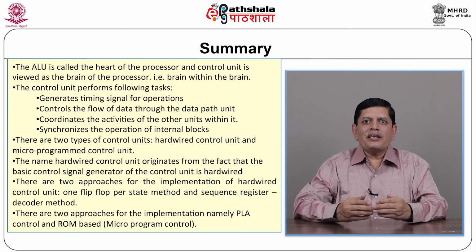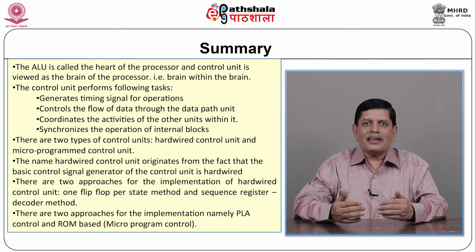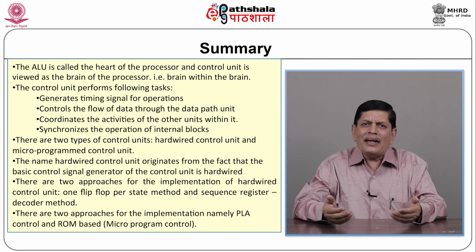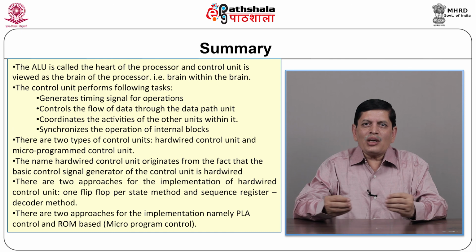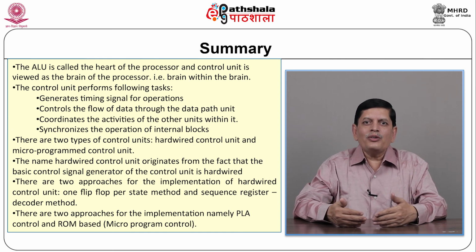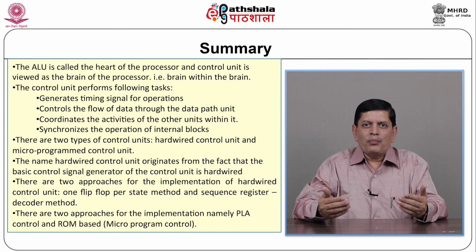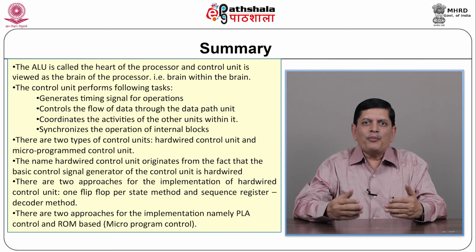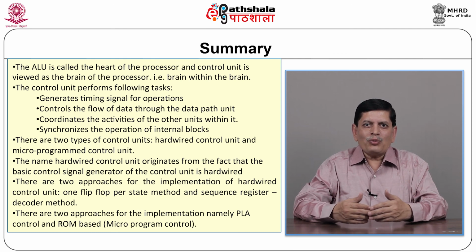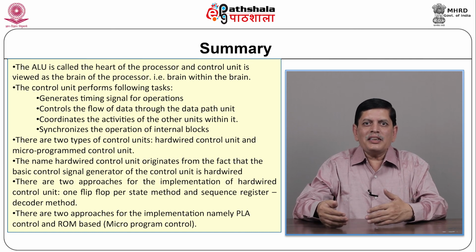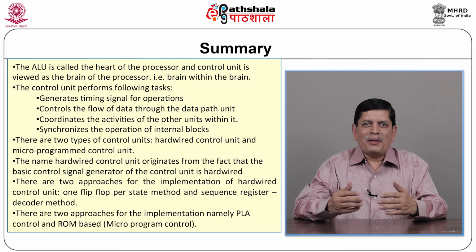The first advantage that is very clear is that if there are any alterations or modifications required, that requires simply changing some of the memory locations or modifying the program, and you can do in situ programming. You do not have to take it into laboratory. You can have field programming that is possible. That is why we can use either PAL, PLA or FPGAs or CPLDs depending upon the design complexity.